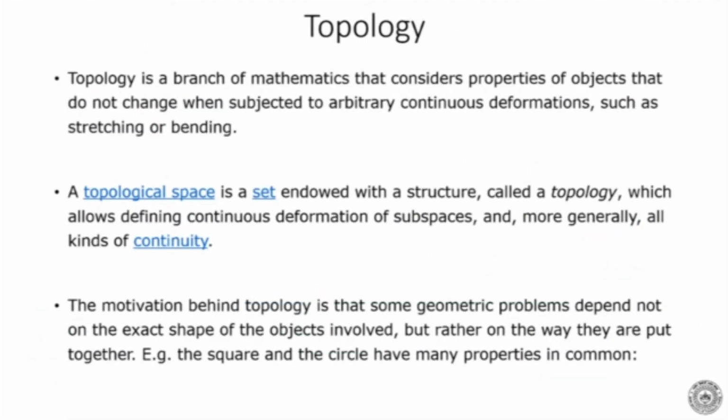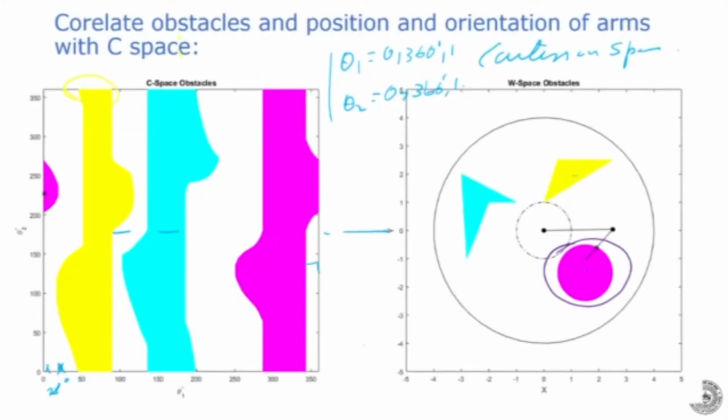So that brings us to the next topic. If you realize, what we are doing here is basically motion planning in our C space, not in Cartesian space. So this is my Cartesian space. Here we are in Cartesian. This is my C space. We are doing the motion planning in C space because the robot is a point now, and everywhere here is free space.